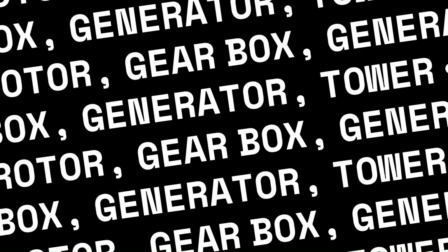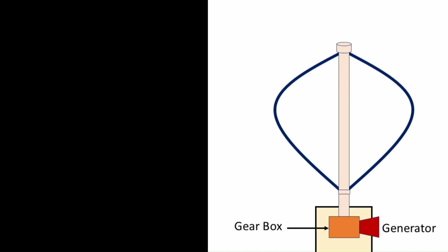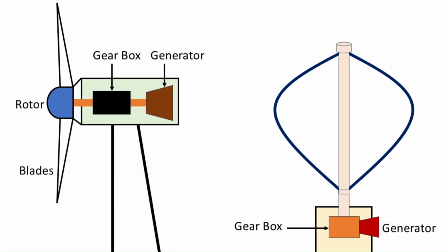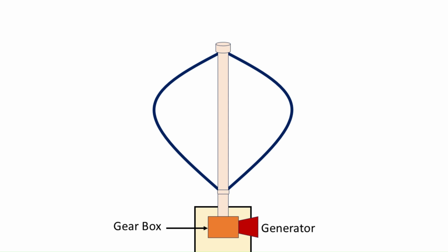There are basically two types of wind turbine: vertical axis wind turbine and horizontal axis wind turbine. Vertical axis wind turbine spins on a vertical shaft, capturing wind from any direction. It typically operates closer to the ground, so we can place heavy equipment like the generator and gearbox on the ground. However, winds are lower near ground level. So, for the same wind and capture area, less power will be produced as compared to a horizontal axis wind turbine.